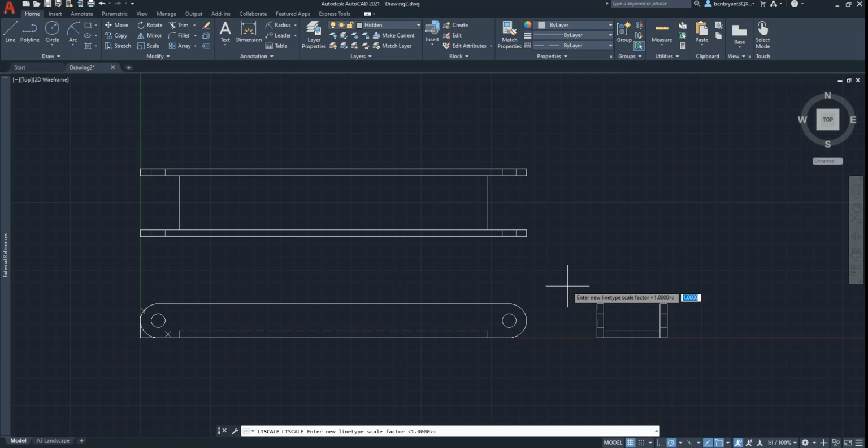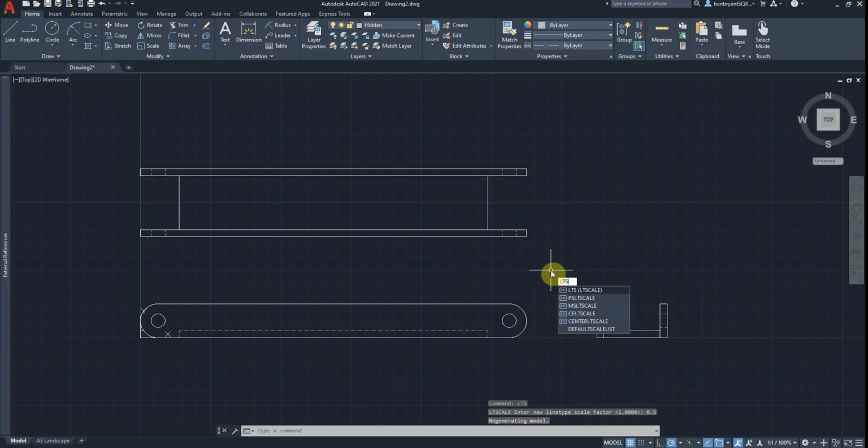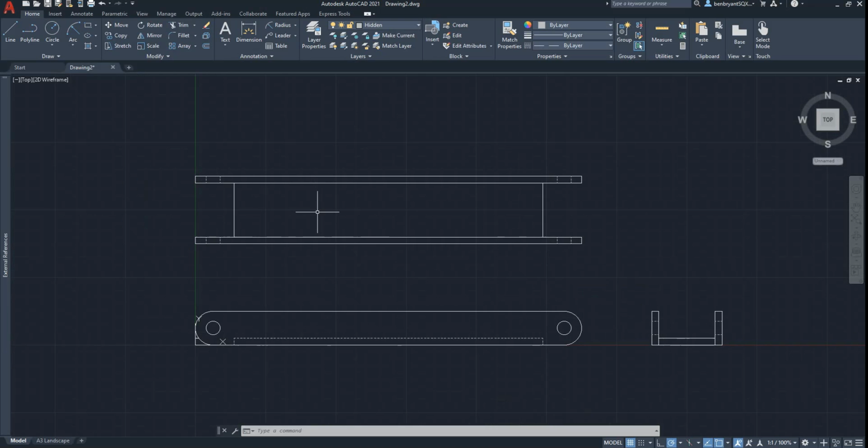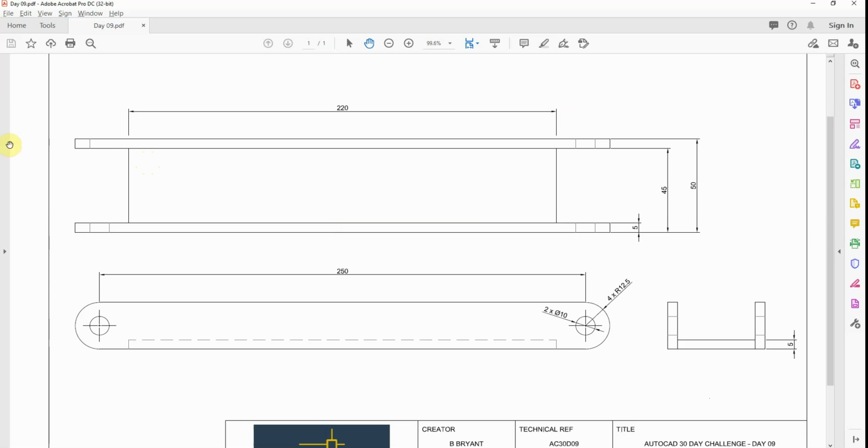What I'm going to do is scale it by half, just to get some more, so I can get those lines now. So I've halved my line type scale, so I can show that these are hidden. I could actually do a bit more lines, could do 0.25, and it'll get more profile. See, it's like little dash lines, which is fine. So that's those components. So on my drawing, it looks like it's a straight through. And actually, I missed that hole as well off on the drawing.